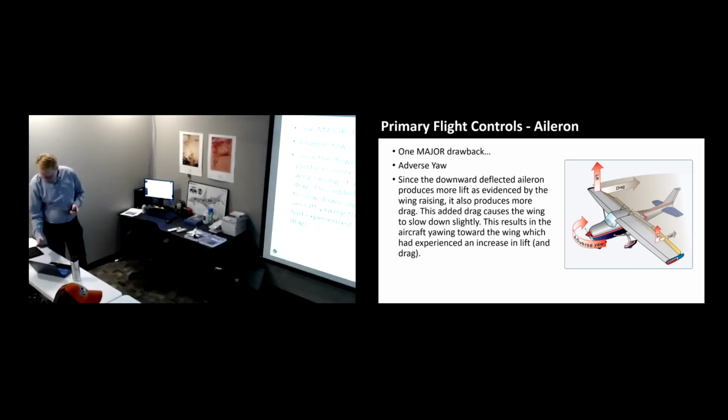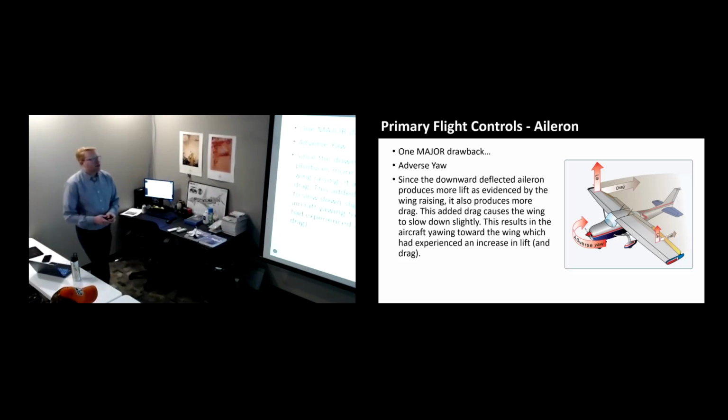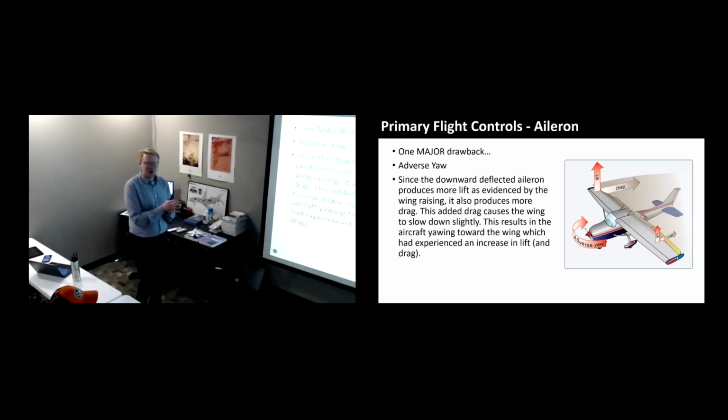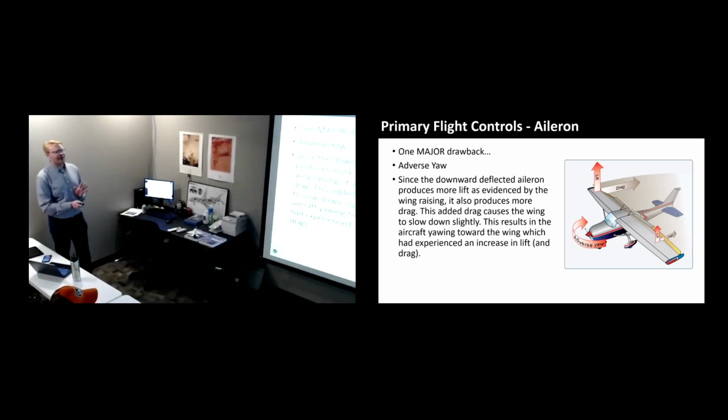Anyone have any questions on that? But is it the opposite direction to the turn? Yeah, it's to the outside of the turn, so the opposite direction you're going, correct? Yes. Okay, so like you said, we'll talk about this in great detail, but if you make a left turn, the nose of the airplane, from the perspective you're looking at, the initial tendency is to go to the right. So when you turn left, that nose will yaw out to the right side of the airplane. And that's all occurring as a result of drag differences as the ailerons move.